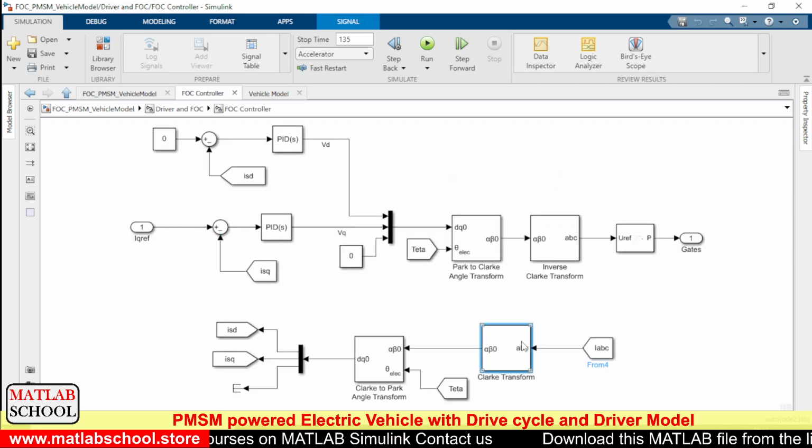will be connected to the Clarke transform. This Clarke transform will convert the three-phase AC signal to a two-phase AC current. Then this two-phase AC current will be converted to direct axis and quadrature axis currents. These direct axis and quadrature axis currents will be like a DC signal. We can use a PI controller only if we use DC current. Comparing two AC signals is not possible.